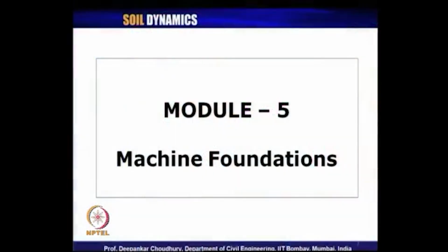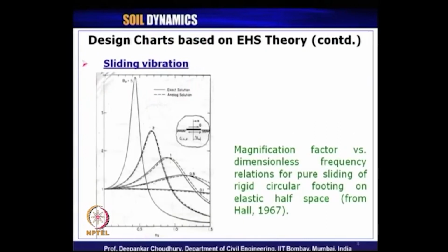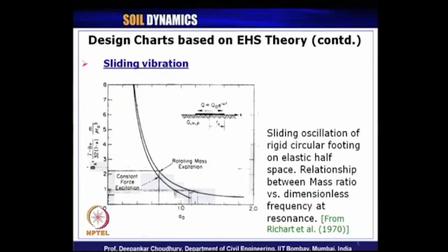Let us start our today's lecture on soil dynamics. We were continuing with our module 5, that is machine foundations. A quick recap of what we had studied in the previous lecture. We have seen the expressions for sliding mode of vibration using Lysmer's simplified analog in elastic half space theory, and the design charts corresponding to that.